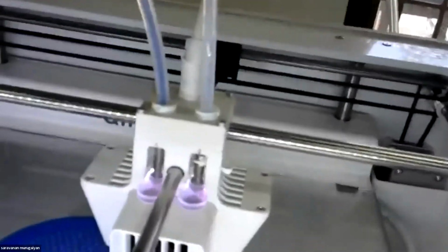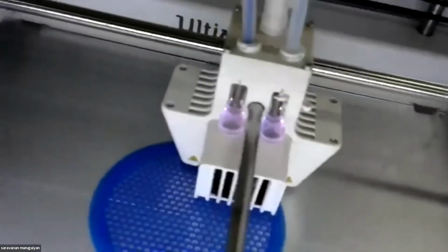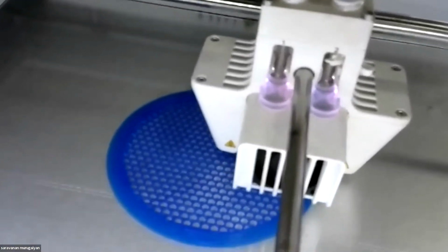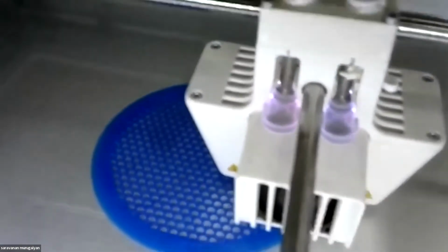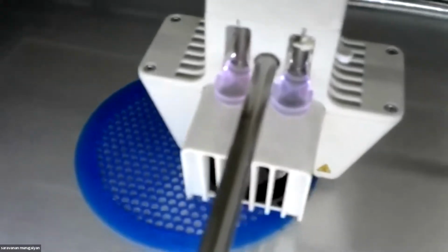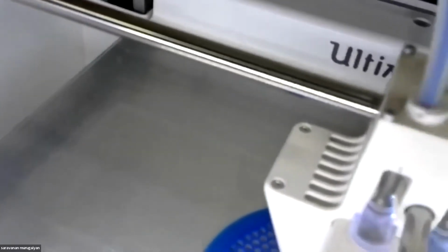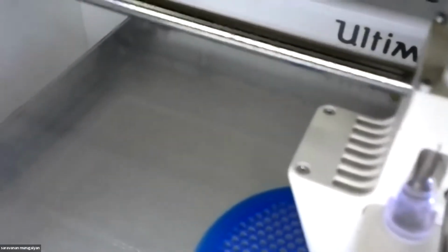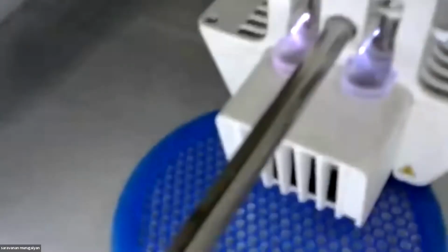And as said before, the component is sliced, and each and every slice will have its separate G-code data. The G-code data is fed into the control unit of the printer. With the help of the G-code data generated, the stepper motors are moved, and the rotations of the stepper motors are properly adjusted with the help of the control unit, with which the extruder is moved in 2 different axes.